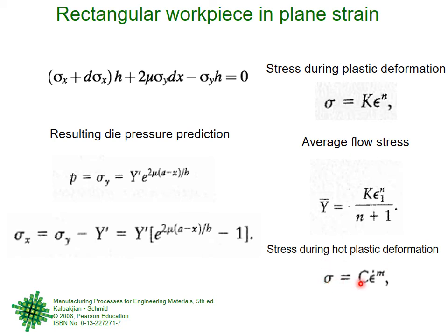So this is that remarkable last one. This is sigma, this is epsilon, strain. But this is epsilon dot, the rate of strain, the change of strain per unit time. If you are applying a strain for 2 seconds, then the change of strain, delta strain upon the time, change in time. This is a strain rate, the rate of change of strain. So this sigma, the stress is not equated to epsilon, it is equated to epsilon dot.